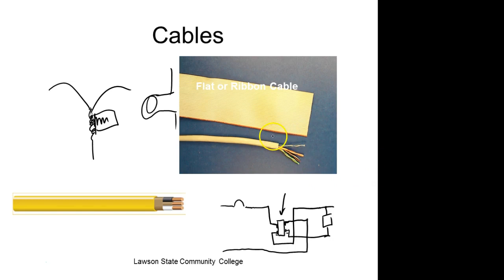These are communication cables. This is called a twisted pair cable. Can y'all see why? Because they're in pairs, and the pairs are twisted together. This is networking cable. So this would be the cable we use for Ethernet, wire Ethernet. That's what we did in PLC3. It could be Cat 5 or Cat 6. Cat 6 is new, but most places are in Cat 5.